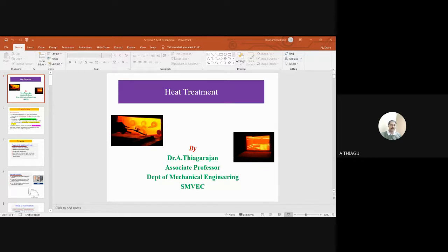Second, you have to make some rapid cooling process. If you suddenly take it and dip it in water, hardness will increase. Sometimes they use different oils, animal oils, fatty oils. A lot of natural based oils are also available. If you dip in oils, the properties vary. So whatever type of quenching you adopt, it will be reflected in the properties of your particular material.